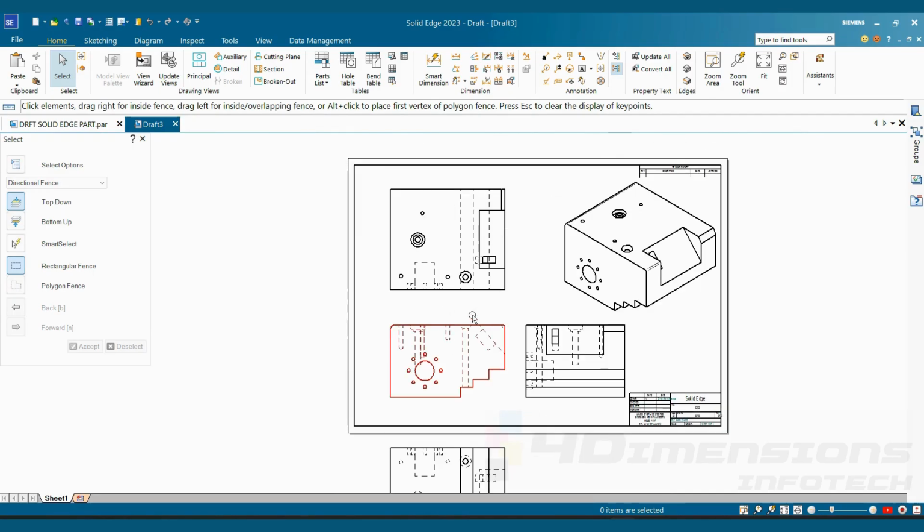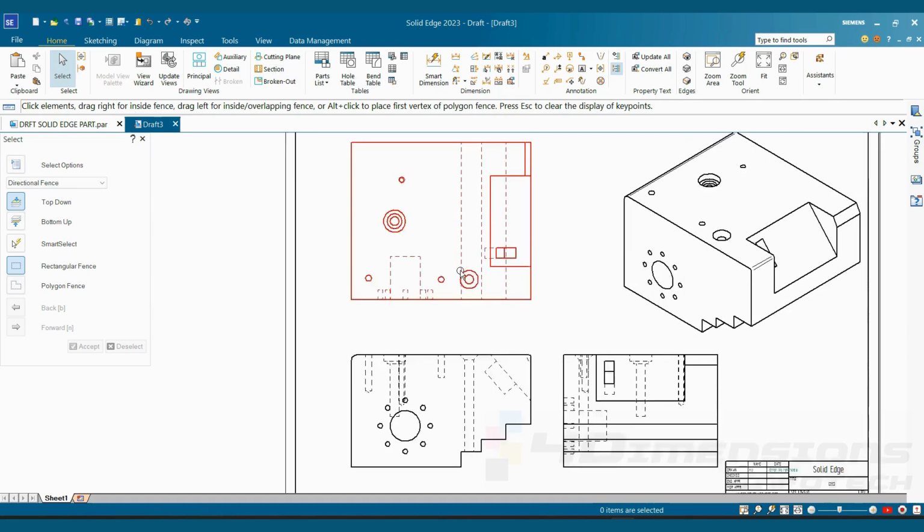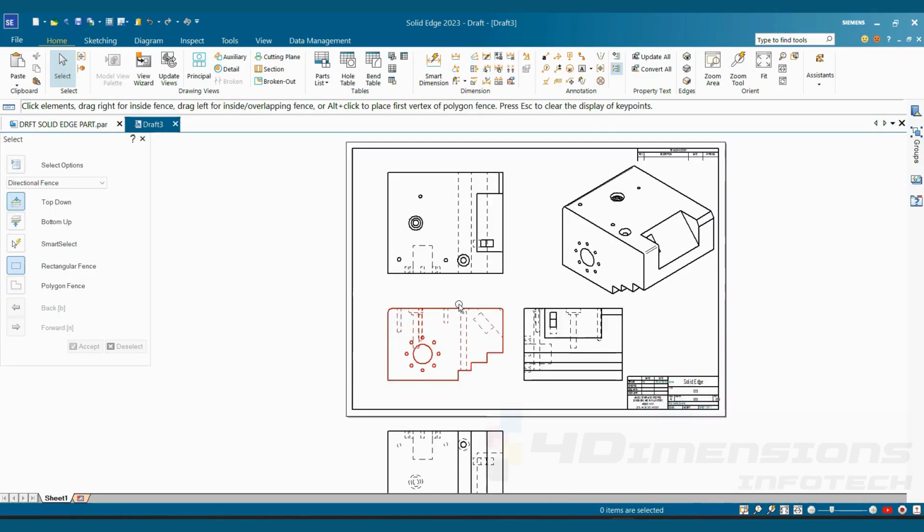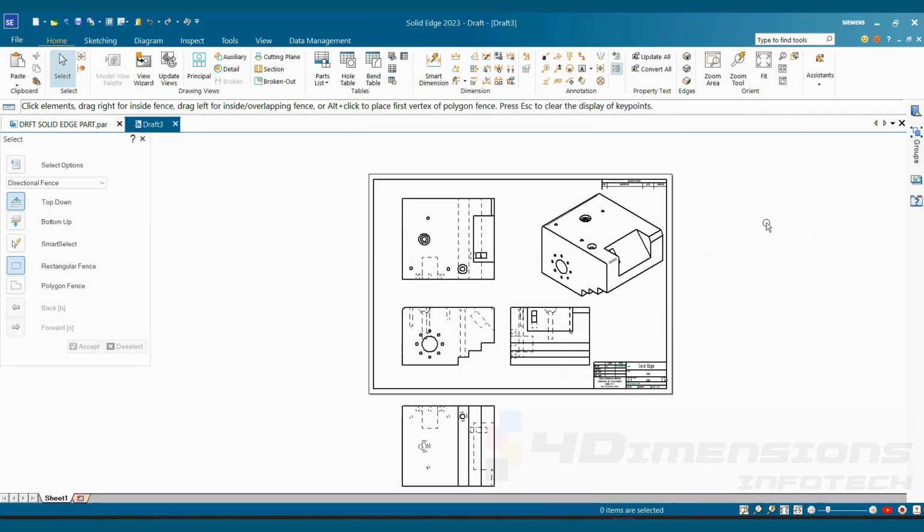In third angle methods, at whatever side we see the view, whatever the features are at that side will be projected in a solid state at that side only. But in first angle method, the views we observe are projected on the opposite side, not on the side from where we are observing. So this is the main difference. In third angle method, the views are presented in the same direction from where we are observing, and in first angle method, views are presented in the opposite direction from where we are observing.